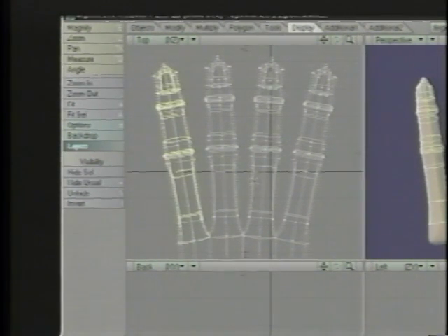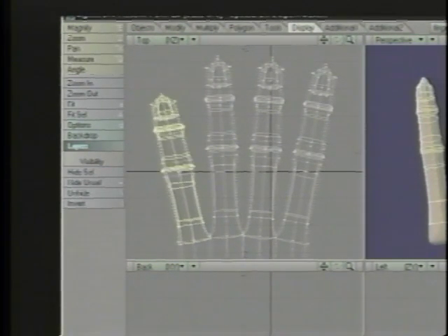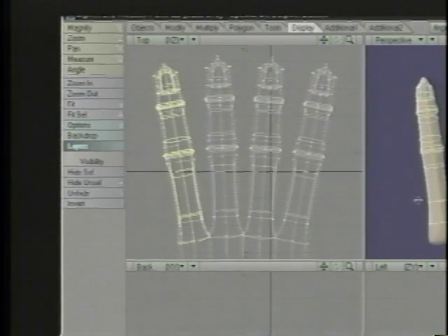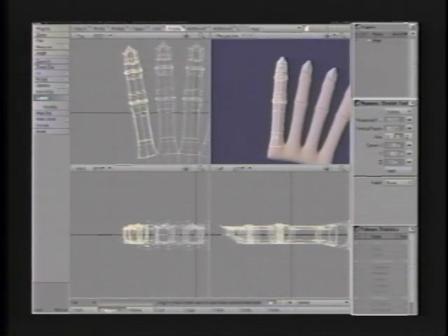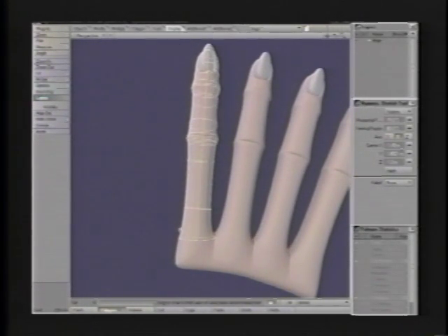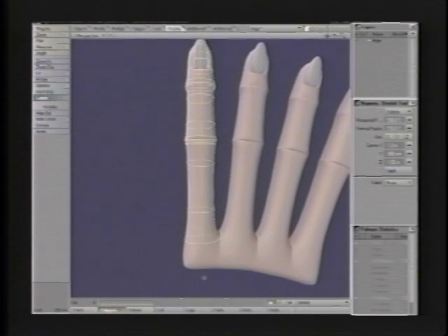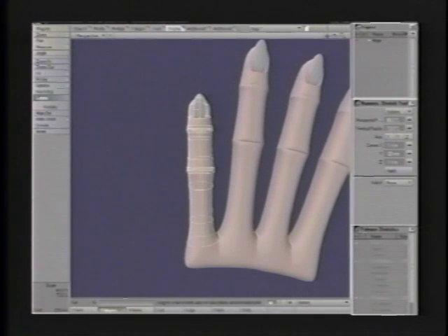expand selection. Now, what you'll notice is, because I'm on an off axis here, if I go to stretch this, watch out as I try and stretch it down. See how it deforms in a strange way? I try and stretch it around, get this really weird deformation. So what I'm going to do is go to my perspective view, and I'm going to rotate it around so that, in fact, let's zoom into this entirely. And like this. I'm going to rotate this view around a little bit until that looks like it's pretty much straight up and down. There we go, using my Alt key.